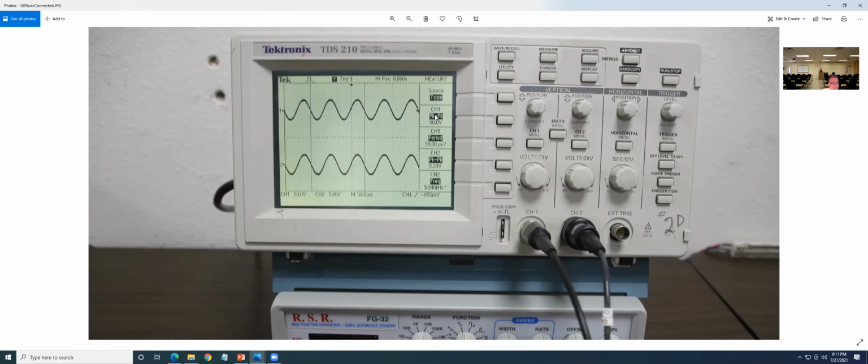How can I set the first window to channel 1? You just tell me, so I know you know how to do it. Can you repeat the question? I want to set this window to use channel 1. You press the button next to that. The channel 1 button or the knob? The top one I can see on the right hand side, the small rectangular one. You press the one that's parallel to the channel 1. Correct.